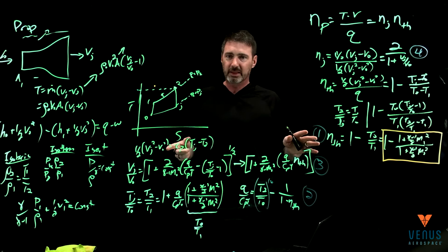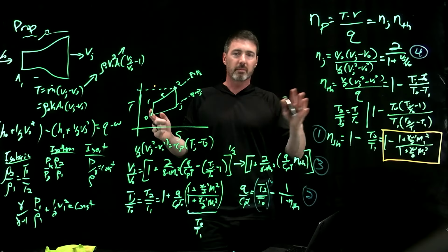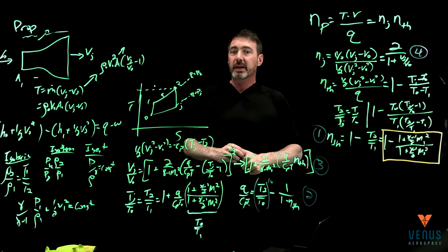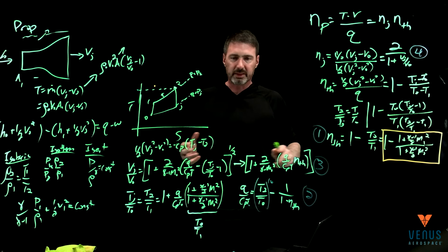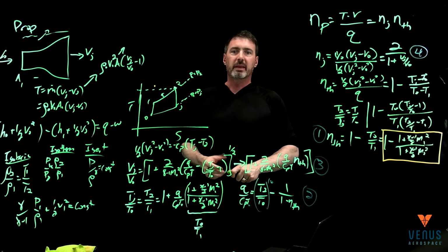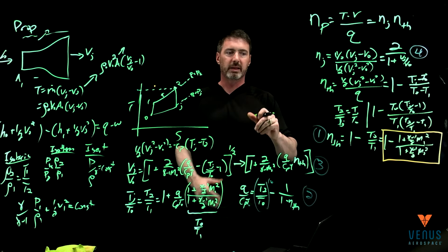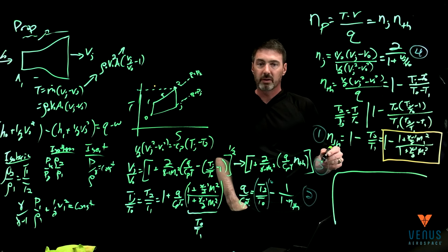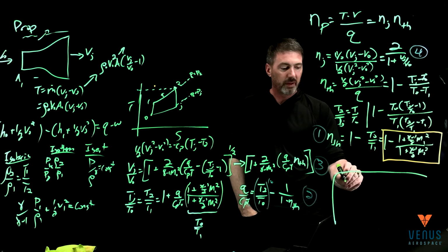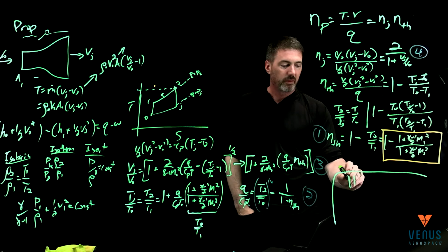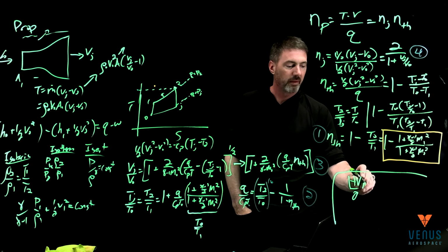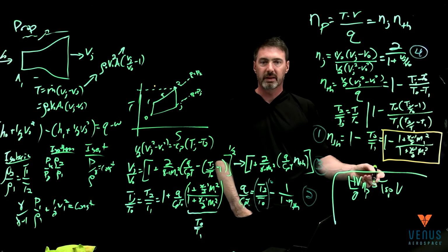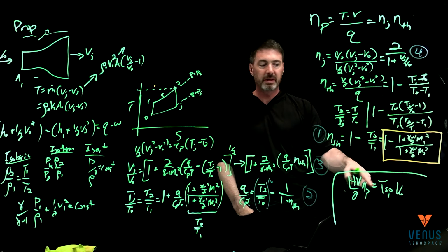And so this is, again, while it's a lot of equations, very simplistic. The only thing we've assumed here is constant pressure heat addition, okay? And the rest just kind of falls out. So when we think through it, I'm going to write down here kind of the big punchline. As you go back to our earlier conversations, within the range equation you have the heating value over g times rate of propulsion. That's the same thing as Isp times the velocity that you're flying at. So if you want to find Isp, well, you're done.